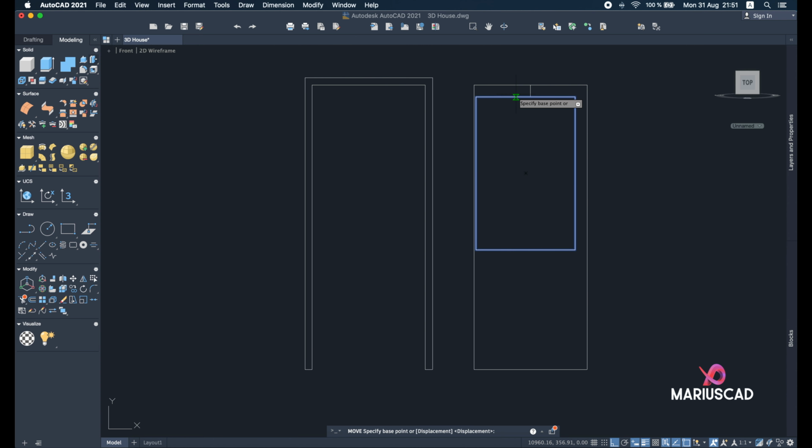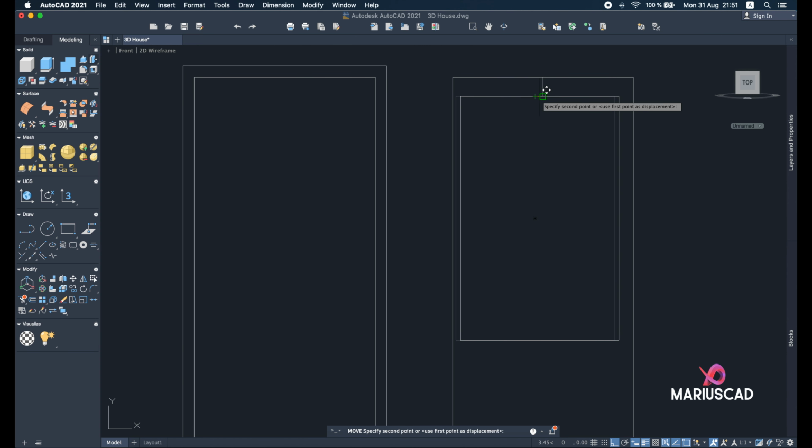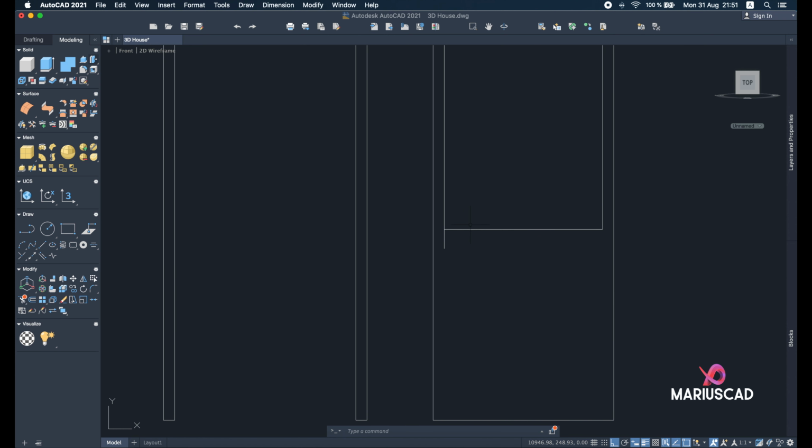No, this is not the middle, but you can switch it. So green, yeah, here we have. Now move this line. Rectangle, another one, but start from here and write 70, 20. Move the line again. Rectangle. Right, 70, 40. And you can delete this line now.